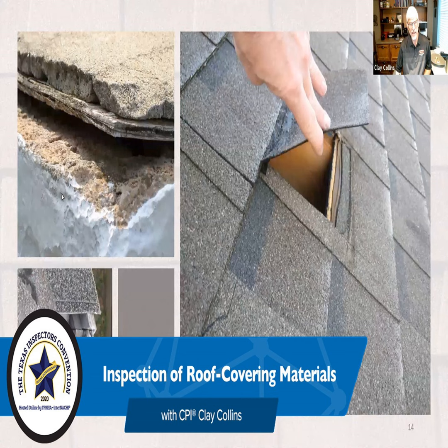And this, in fact, looks like a worse condition because water can run down. And even though it should be lapped, right here it isn't. So this is something you'll never be able to see, but you can see the impact and assume that there's some problem in the way it was installed.